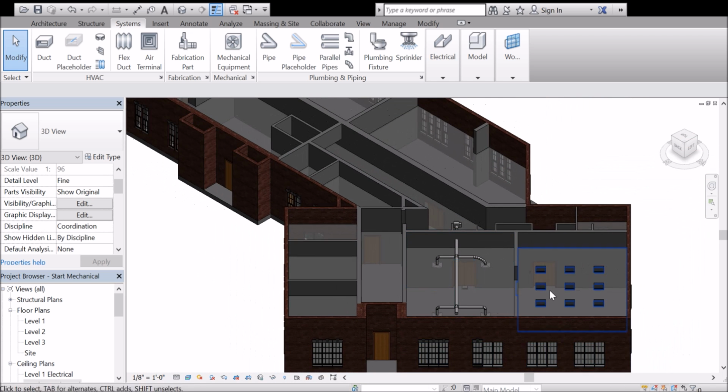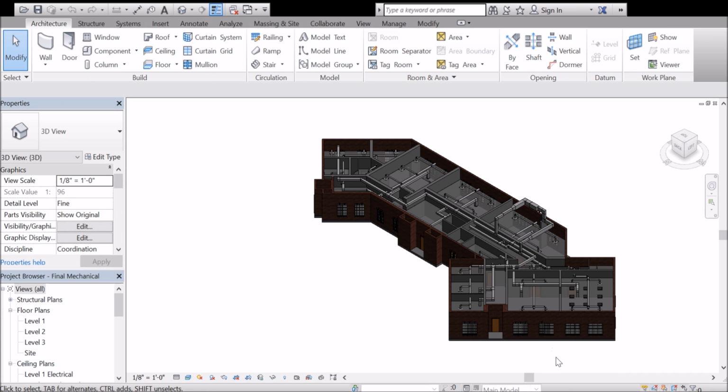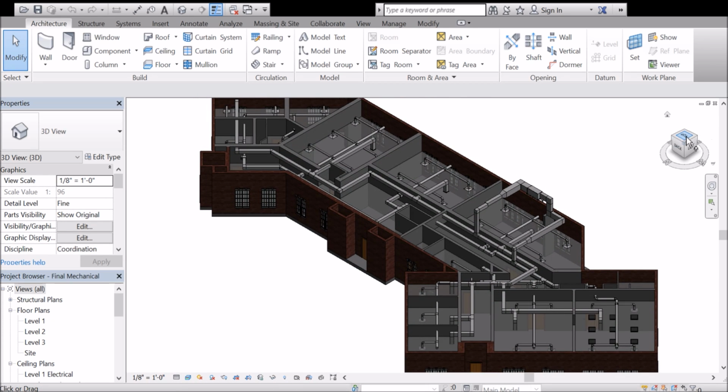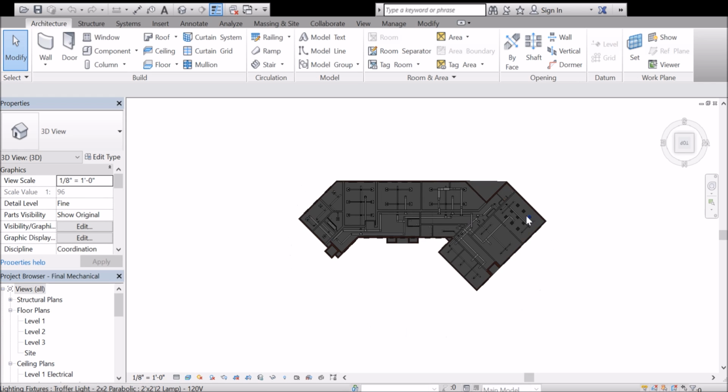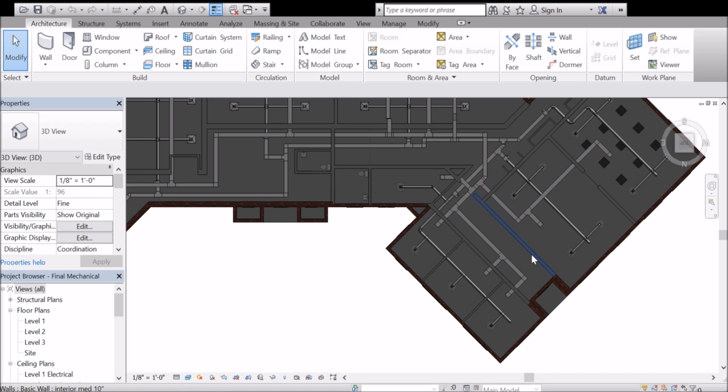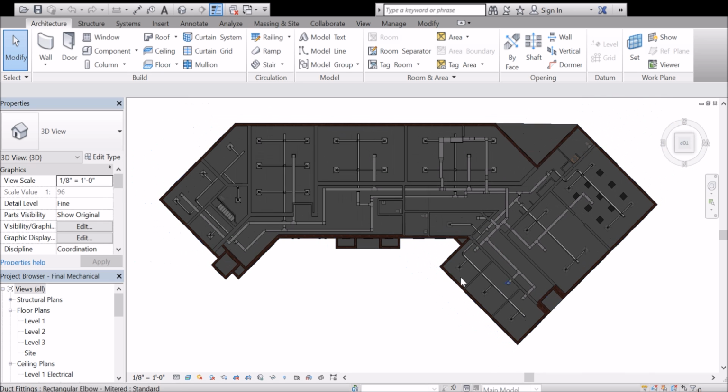So you're going to want to do that with every single one of your rooms. If we jump on over to kind of a completed model I have right now, you can see how things are going to fill up pretty fast here. So for me, I used 7 VAV boxes throughout this building. This room has its own VAV box. The room we just did as an example has its own VAV box. I grouped these 4 rooms here together and put them on one box. And then the 2 big rooms each got their own. This room got its own box. And then this group of 4 rooms over here got a VAV box.